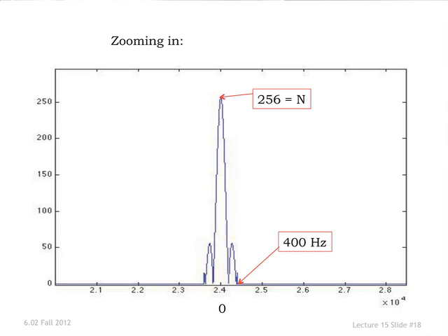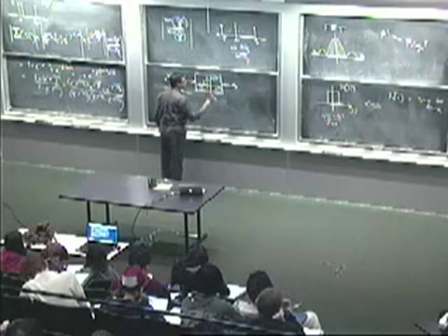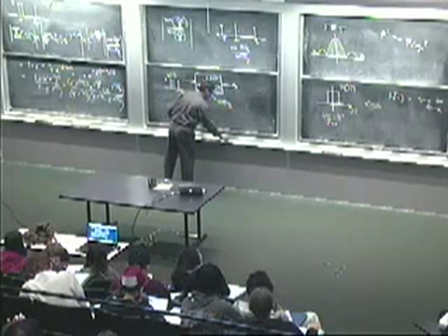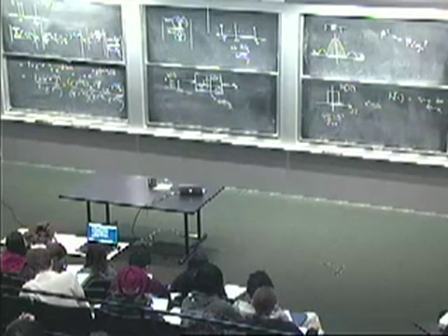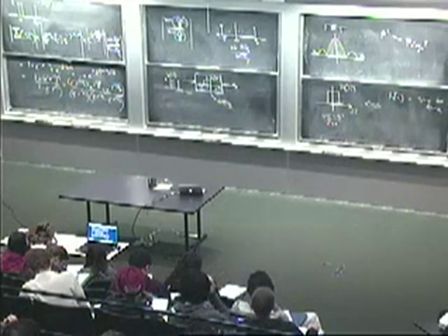I've taken a low-pass filter where this cutoff corresponds to a cutoff at 400 hertz, if you're thinking in terms of the underlying waveform. So what we've done is take the rectangular pulse and put it through a low-pass filter, and I'm assuming an ideal low-pass filter that passes everything in this frequency band and nothing outside of it.